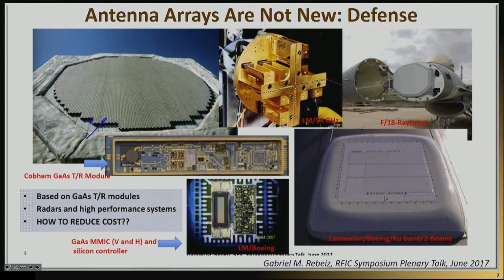So those type of antenna arrays are outputting immense amount of power to basically detect threats from far away. And as you can imagine, this type of antenna array can actually scan with an amazingly small beam width. And we have learned in this class why this thing has to be large, right? So we have learned that the beam width will actually be proportional to the diameter of this thing, right? It's the same idea of creating an aperture, except now you can control the pixel of the aperture, all pixels of the apertures. Military aircraft have this type of antenna arrays to detect threats, and other aircraft. And even in radar systems, in civilian systems, we will actually use this type of antenna array sometimes.